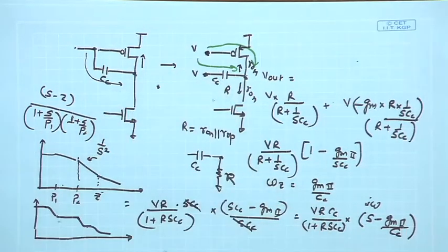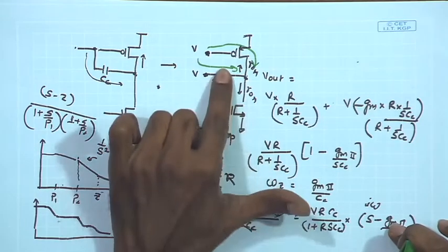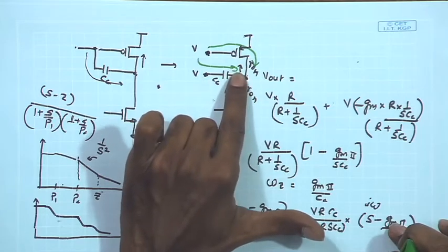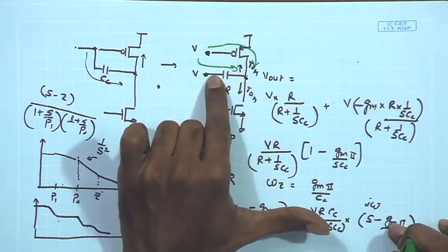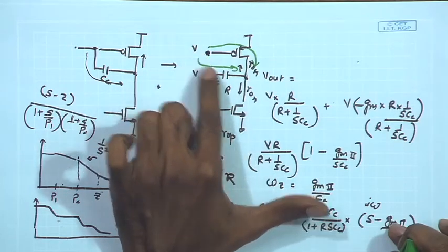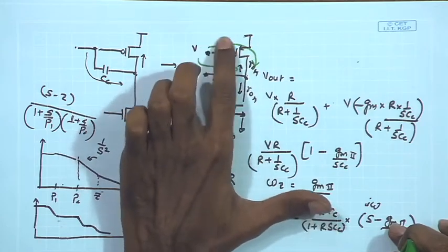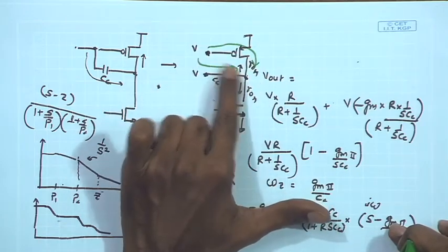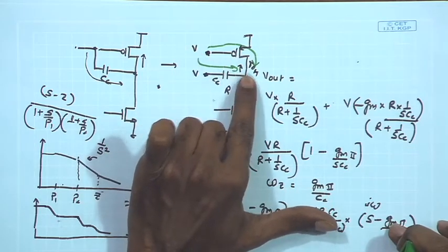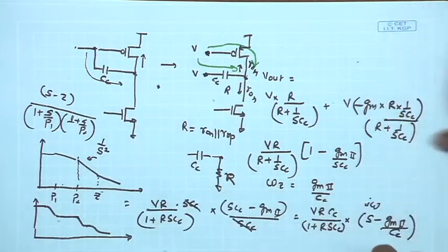So, that is one strategy, one possible scheme used to compensate this kind of circuit, and in order to do that we can think of inserting some component over here which can block the second path. So, basically we want to eliminate the signal transmission from the input to the output through one of the path. Of course, this is not that path because this is the amplification path, we do not want to disturb this path, but this is an undesirable path through which the signal is propagating from the input of the second stage to the output of the second stage, and if we can block that, then we can succeed in our stabilization.